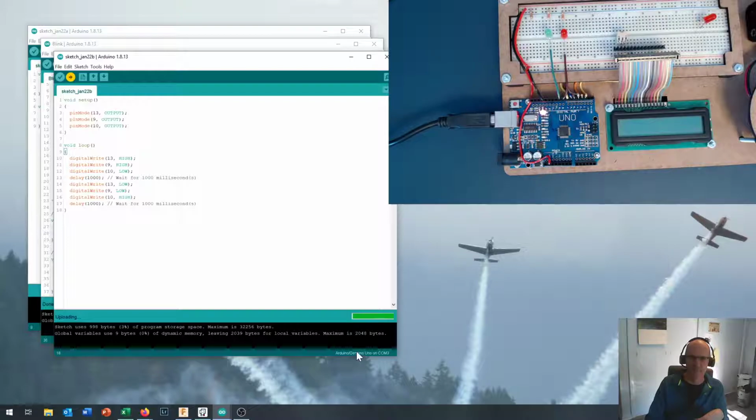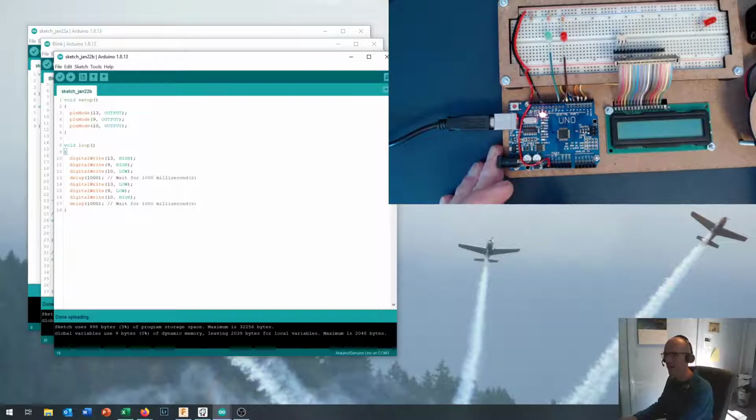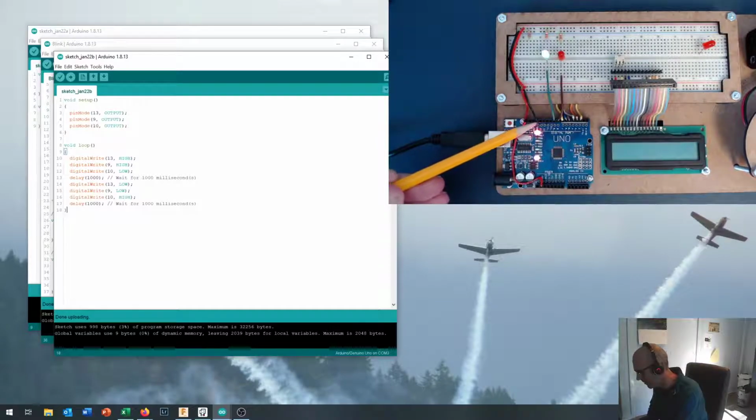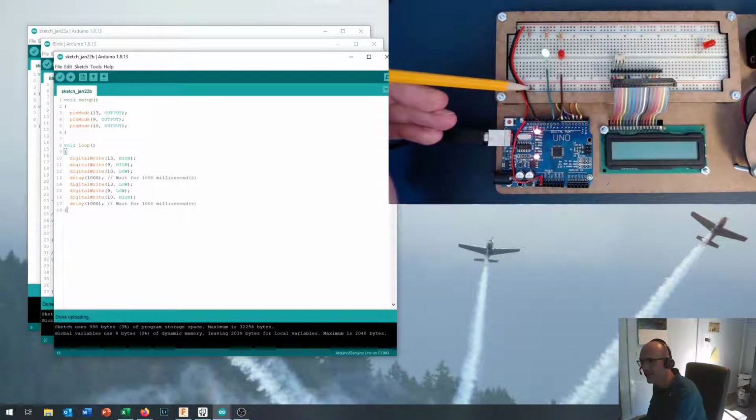It compiles your sketch and moves it over to your Arduino Uno. And now I have, darn it, one green light blinking. Okay, now you'll notice that I did a little bit of work on my breadboard before getting started, and it's the exact same wiring that we talked about in TinkerCAD. So I've got a black wire coming from right here into my ground line that runs right along here.